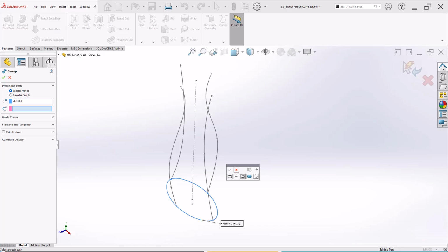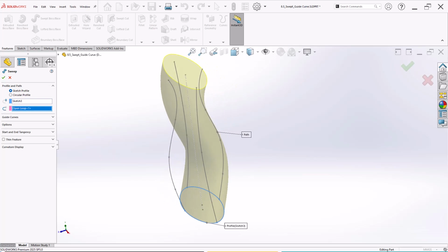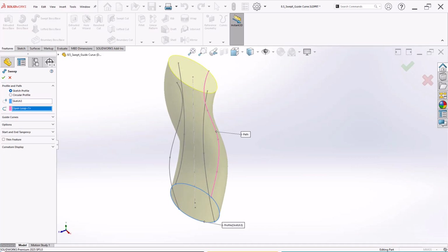Here, out of these 4, I will choose, let's say, this as a profile. The moment I do that, the problem is, along with this sketch, one more sketch geometry is added in a single sketch. So here the selection toolbar asks me to choose either closed loop or open loop. So I will choose this and right click. Otherwise, it is not allowed to select this individual sketch because 2 sketch geometries are in a single sketch.